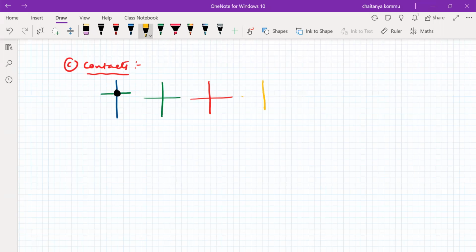So, and P diffusion, contact is required. For example, we have a P diffusion, we have a metal here. So unless we have a contact cut here, there is no connection at all. Okay, so these are all connections. So therefore, contacts. These are all connected contacts, right? These are not a transistor formation, please remember.